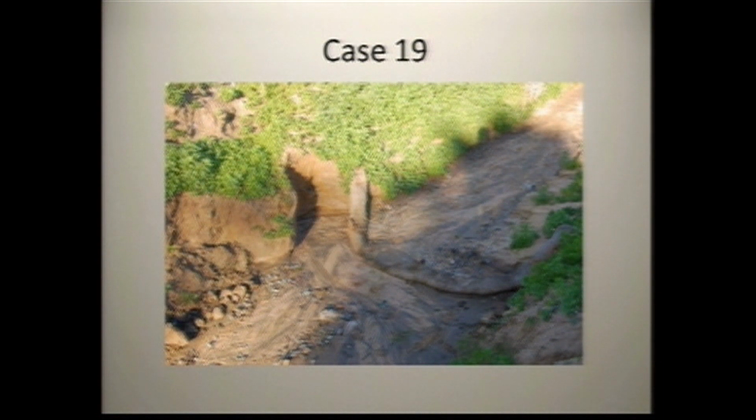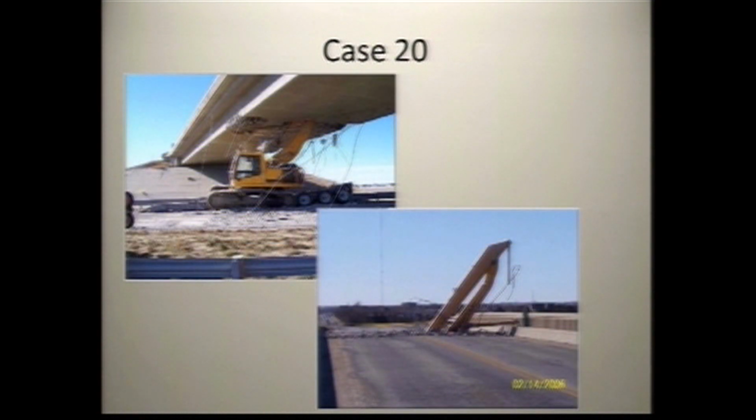You can see that the water piled up and then it couldn't go anywhere, so then it just blew out to the side and created additional erosion. If they hadn't done anything, we would have been better off in this location. Wrong tool for the job. Straw wattles are a contour device, a sheet flow device, not a concentrated flow device.